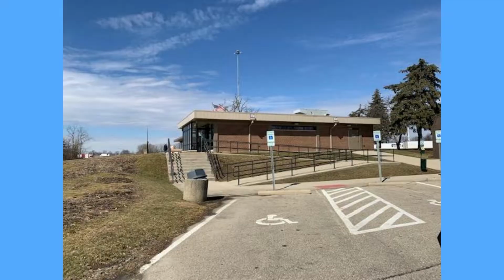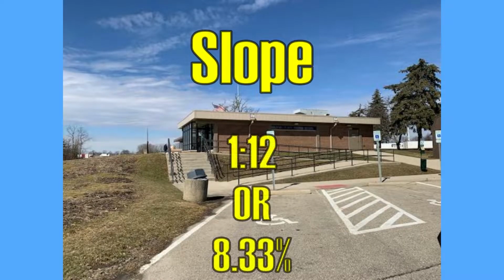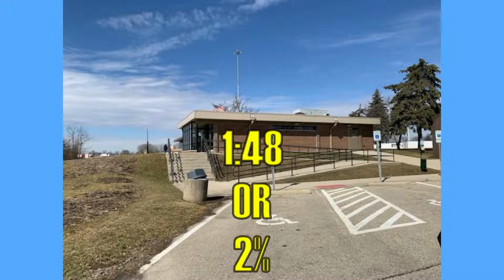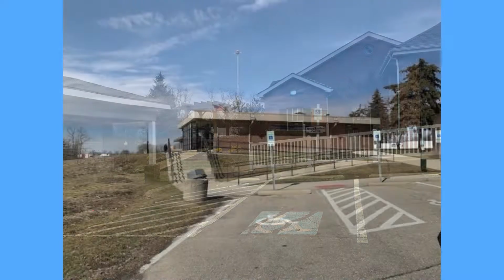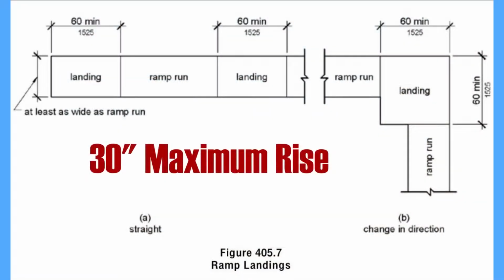Ramps on an accessible route shall have a slope no greater than 1 in 12, or 8.33%. Cross slope cannot exceed 1 in 48, or 2%. Floor and ground surface must be firm, stable, and slip resistant. The clear width of the ramp run shall be 36 inches. The maximum rise of any ramp run shall be 30 inches.